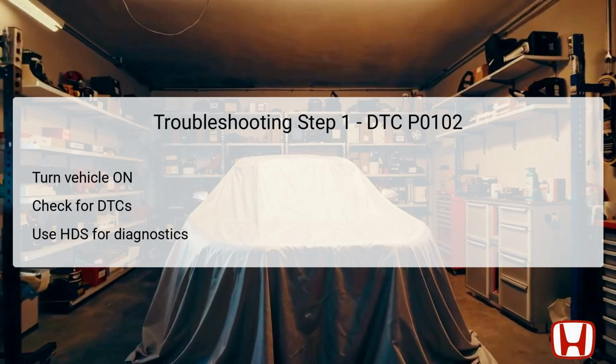The first step in troubleshooting DTC P0102 requires the technician to turn the vehicle ignition to the on position without starting the engine. This initial step ensures that the vehicle's systems are powered and ready for diagnostic checks. Next, the technician must utilize the Honda Diagnostic System, HDS, to check for any confirmed or pending DTCs. This step is important to understand if other issues are present that might correlate with the MAF sensor problem.